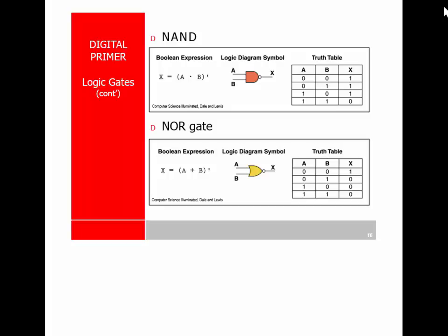What that basic rule says, in a nutshell, is that I can take any digital function and I can do it with nothing but NOR gates or nothing but NAND gates. I don't need AND gates, OR gates, XOR gates, or inverters. I can do everything with just NAND gates or just NOR gates, one or the other.